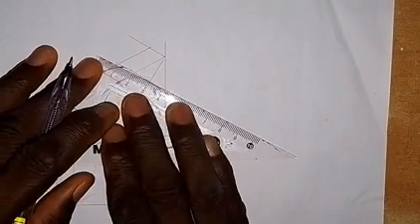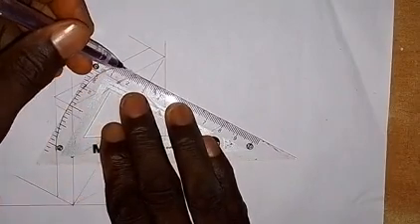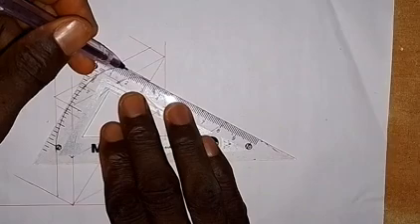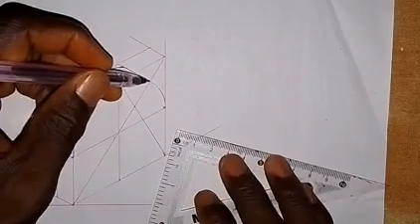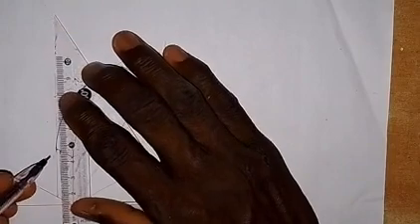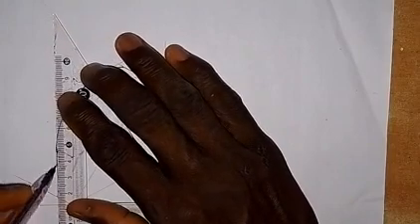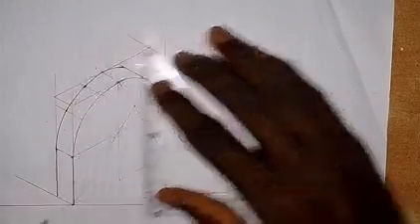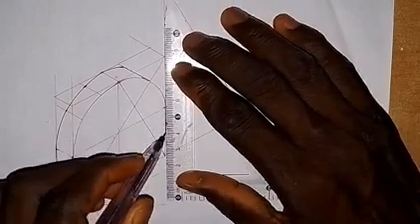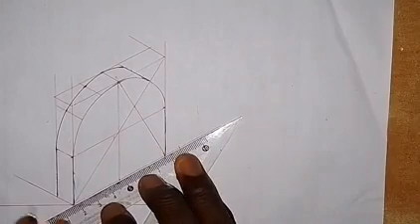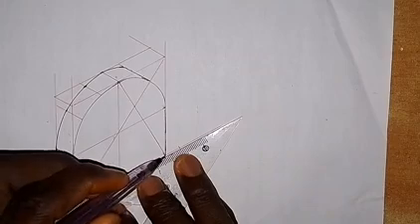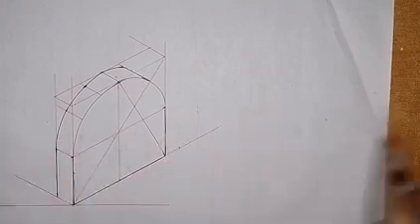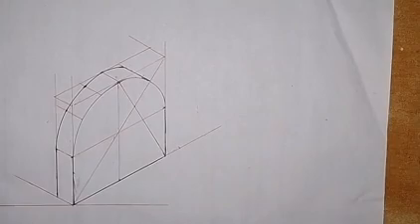So this line now, you make this line a thick line, from here to here. Let it join this diagonal line, and then we are going to make this line a thick line, and we also make this line a thick line. This line also, we make it a thick line. Okay, and this line here, we also make it a thick line. Alright, so now we have a circle here in the center whose diameter is 30 millimeters.